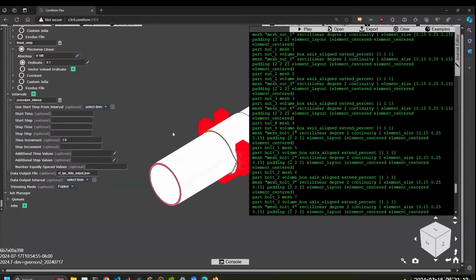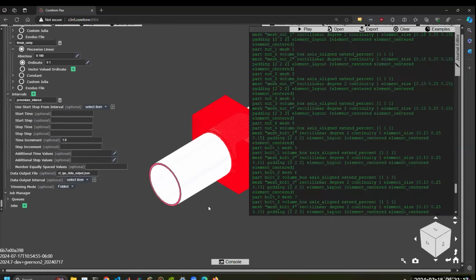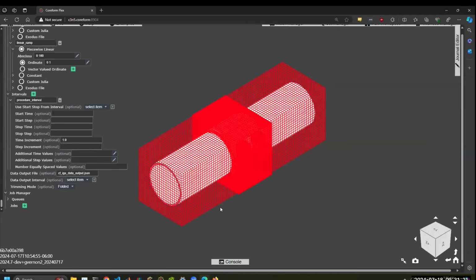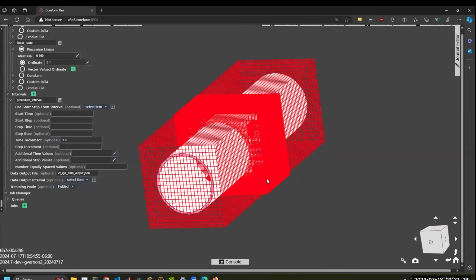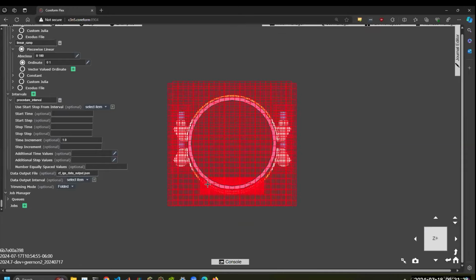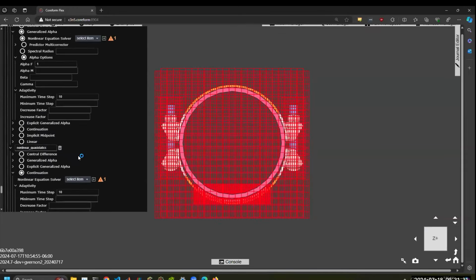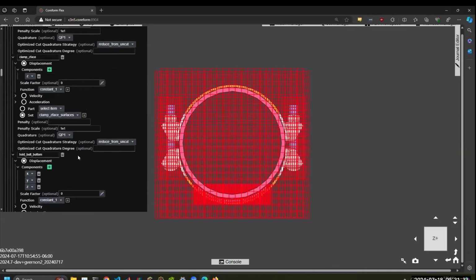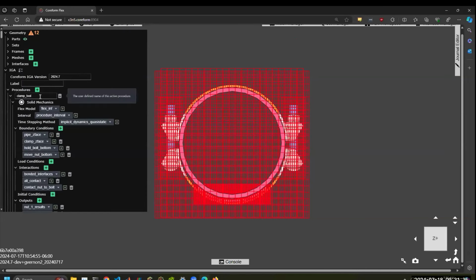So now the meshing is taking place in Coreform Flex. And you can see each of these individual parts is, in this case, just showing a fully immersed approach. As we mentioned earlier, for simple shapes like the pipe, we could have just done a full body fit mesh. Again, the goal behind flex meshing is that when it's trivial to build meshes, when automatic or semi-automatic meshing tools can find body fit meshes, that's generally preferable.